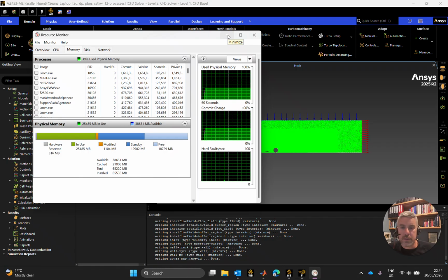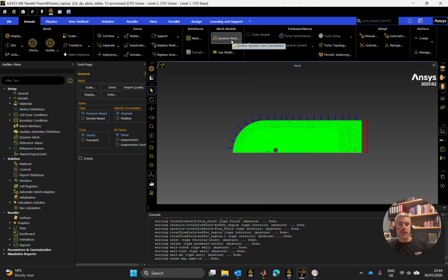Okay, so let's just drop that down. And generally, we'll look at that as the flow field is being solved. All right, so let's go down this here. This looks to be loaded in okay. And on the outline view, I generally work from the top to the bottom, albeit that I'm going to write in a couple of report definitions before I go in and change any sort of boundary conditions here, which I'm going to need. But in general, everything looks good. I'm going to run a steady state.